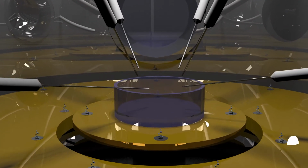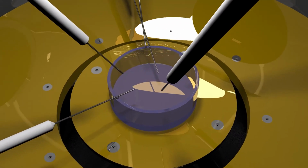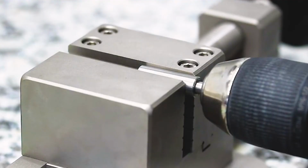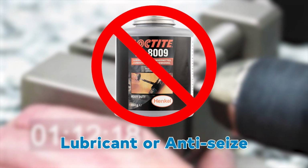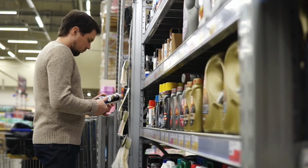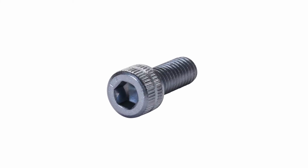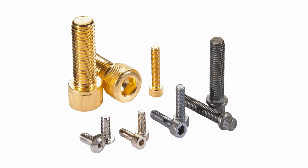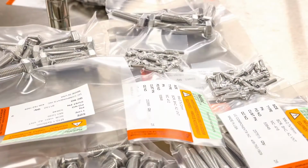This phenomenon is not exclusive to vacuum and can happen in many process environments, particularly those in which lubrication is limited or not permitted. How do you prevent galling? The best way to avoid galling is to use a lubricant or anti-seize. However, in UHV or other clean applications, the use of anti-seize lubricants is not an option because of the possibility of contamination. In these instances, you will need to use a fastener finish that is designed to prevent galling, such as those offered by UC Components Incorporated ReadyVac lines. Utilize parts that are made from alloys that lower the possibility of galling, or another solution.